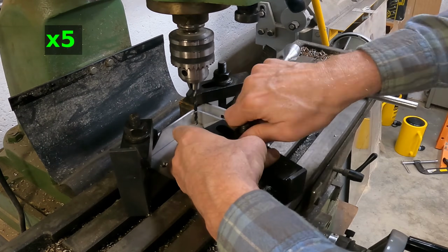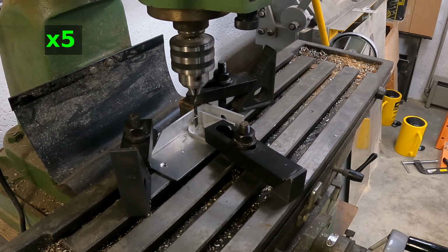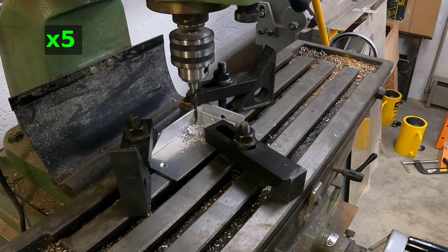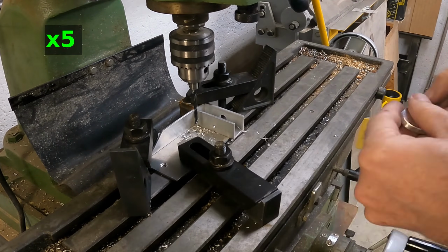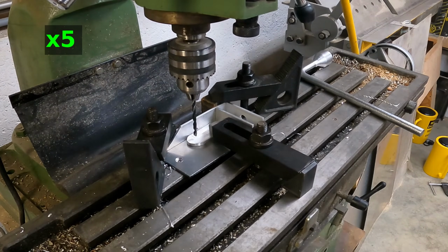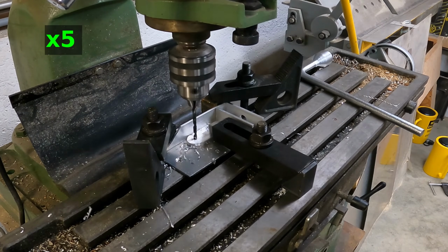And now we get the chance to start drilling holes. To start, we're going to drill holes in the ties that transfer load from one tier of load spreaders to the next tier of load spreaders. And there's one hole in each end. Not too big a deal. I'm going to drill these holes 1/2 of an inch from the end on each end.